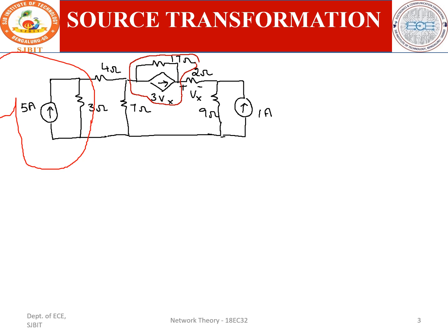So after converting the voltage source, you can write like this. V is equal to I into R, 5 amps into 3 ohms, therefore it becomes 15 volt, and this resistance 3 ohms will come in series, this is the 3 ohm, and this 4 ohm as it is you write, and the remaining circuit you write, that is 7 ohm, it is there from here.